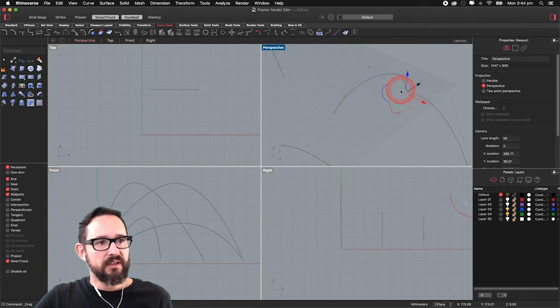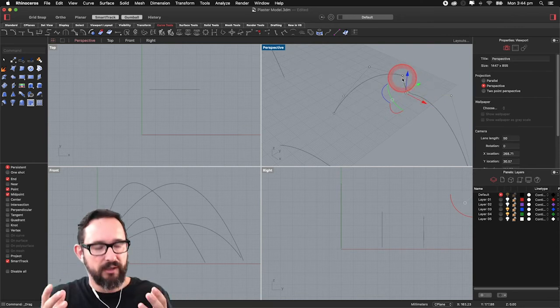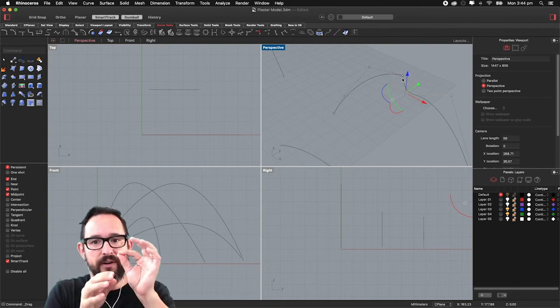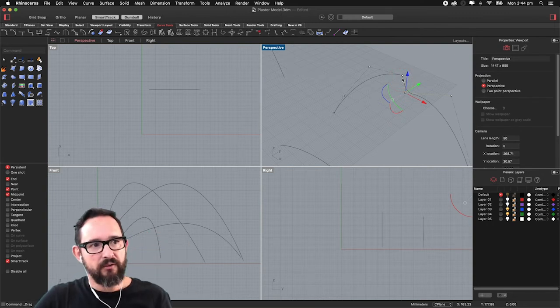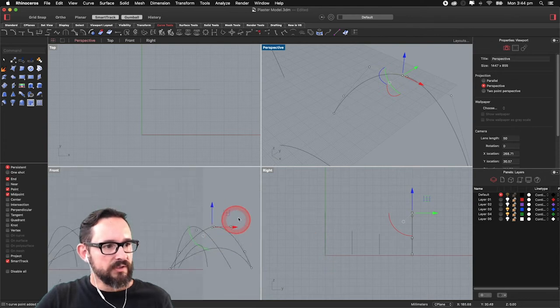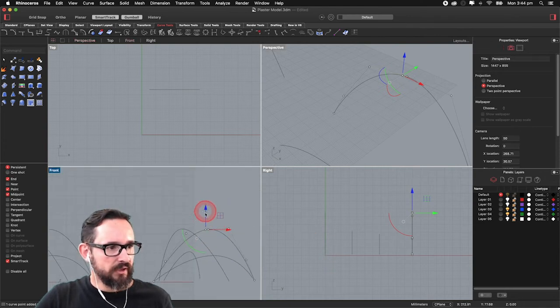So you see these are the control points. It's not the kink, it's that one. So this just keeps on controlling that, but it creates a break in that curve. So it allows it to create a kind of edge or a vertex that will start another curve, but it's a connected curve. So I'm going to undo, and actually what I want to do is move this one downwards. So in this case, I'm going to move this one, and it will create